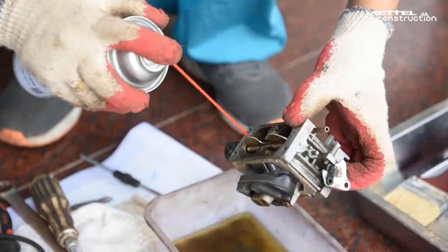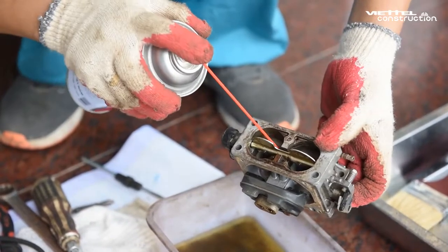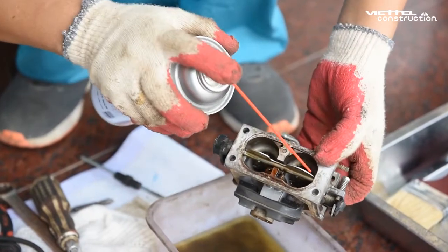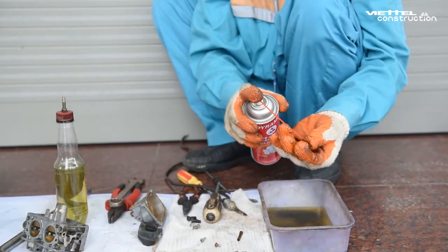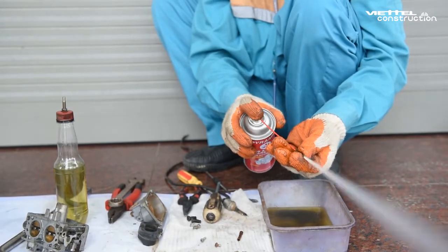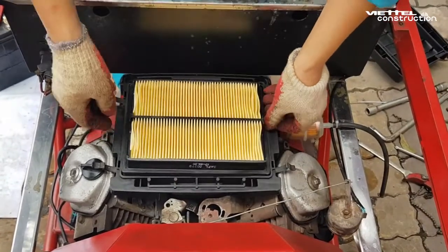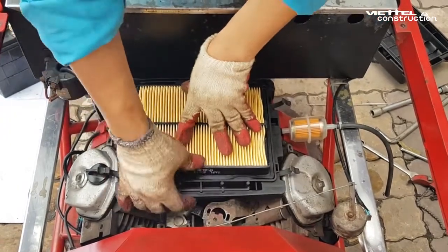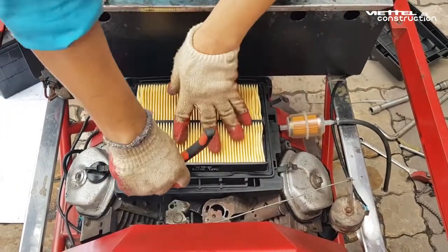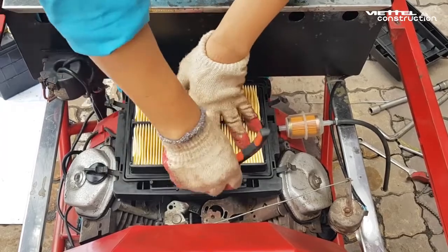Check and clean the carburetor, air filter. Make sure the seals, gasket are tight, clean solenoid, main jet, nozzle, air inlet and gasoline lines inside the carburetor. Note: when cleaning, it is necessary to avoid damaging, tearing or deforming the seals, gasket in the carburetor. If you cannot recover, replace it with a new carburetor.